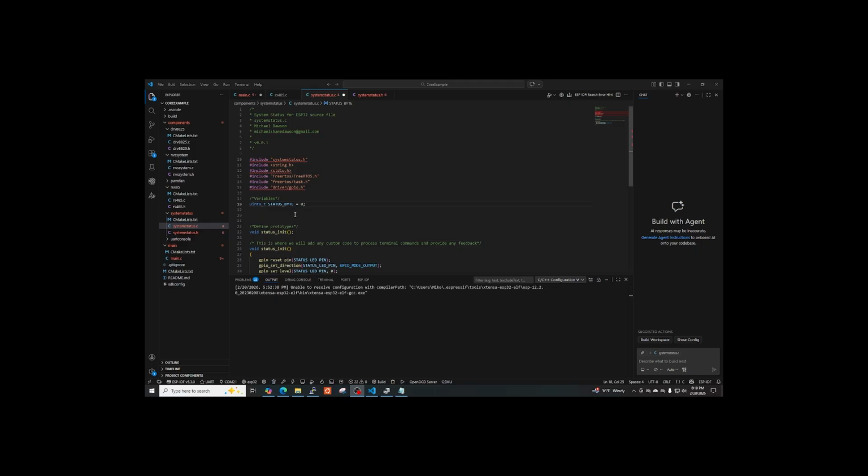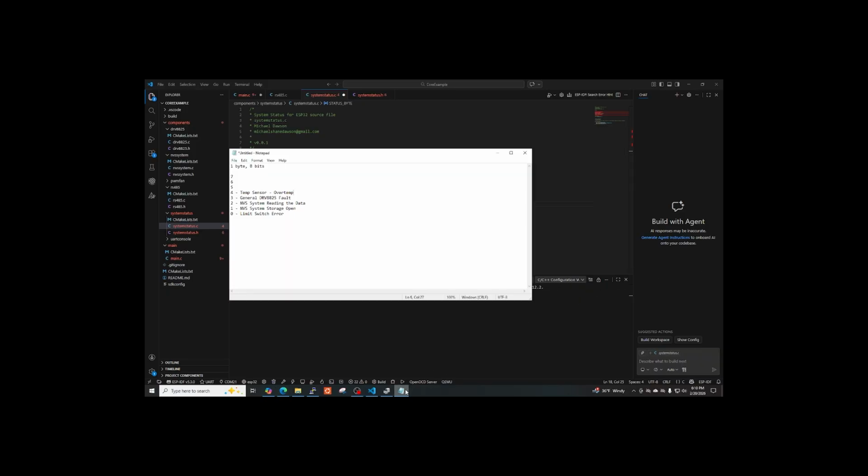So we have the status byte here, and we've got 3 more bits that we can use for things. When we go to write the temperature interface, we could set it up to monitor the tach on the fan.